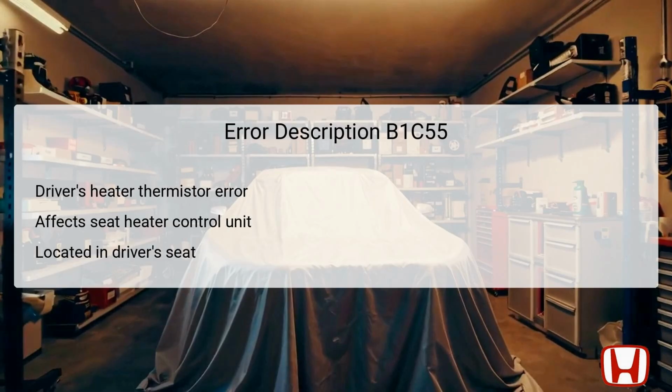The error code B1C55 indicates a malfunction specifically related to the driver's heater thermistor circuit. This thermistor is an essential component of the seat heater control system, allowing for temperature readings that inform the unit when to activate the heating function.